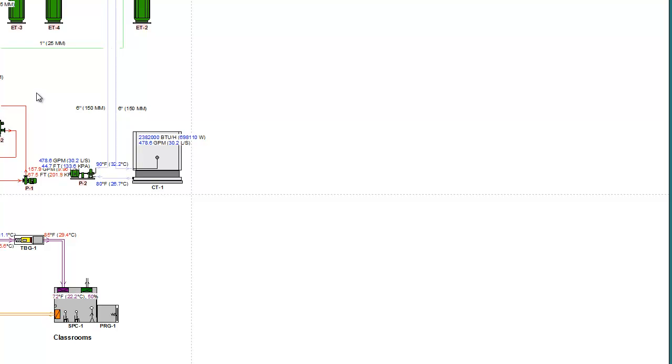And then you know how to connect the components in the 3D Revit model. The data from HVAC solution can be put in the shared parameter data of Revit. Then you can use the Revit schedule formats, which we automatically create for you in Revit, to have your schedules created in Revit. So this is what HVAC solution does.